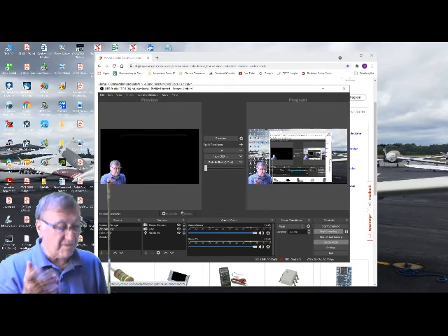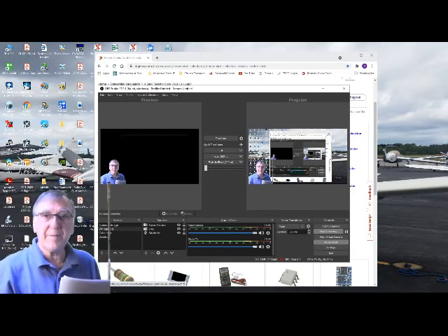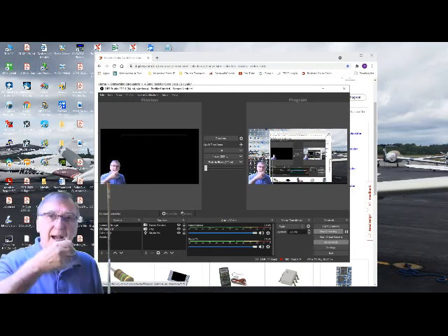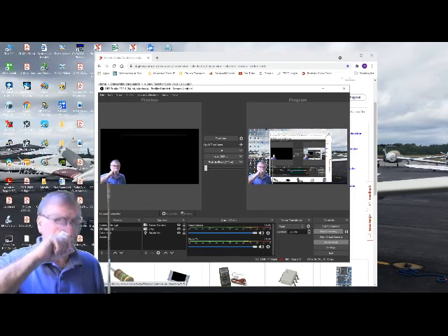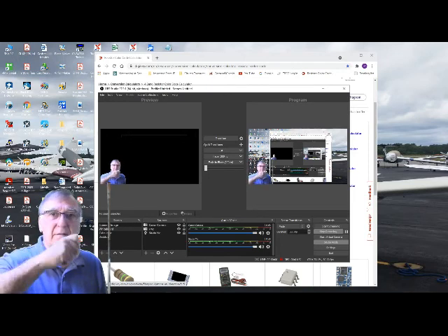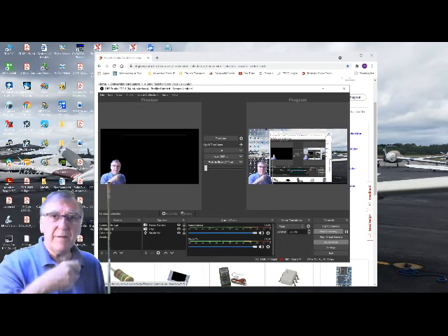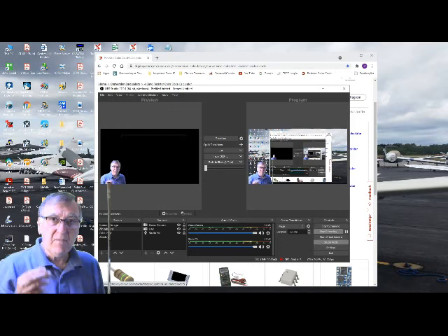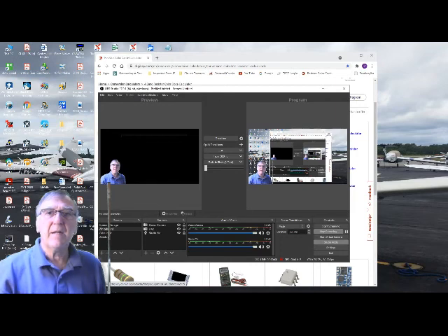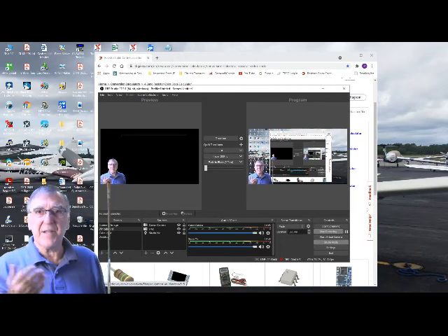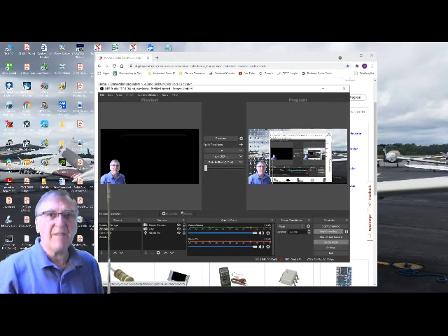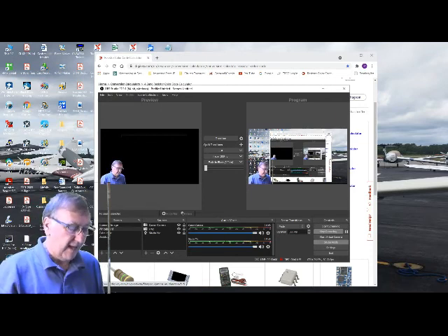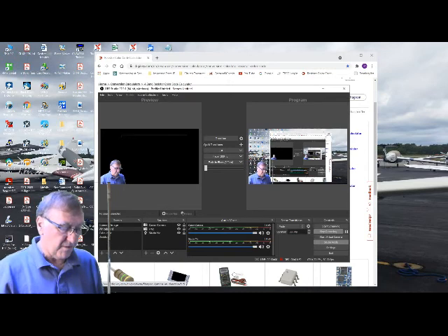So now, there's also variable resistors. That would be like a volume control. You know, they're metal with a shaft, and inside there's a wiper and either a wire coil or even carbon. So as you turn that, the resistance changes. And some are 3-terminal, as in the case of a potentiometer, where the resistance goes down on one side with respect to the center. Remember, 3-terminal, and then it goes up on the other side. So they're used in a lot of things. Radios, a lot of electronics have variable resistors of some sort in them.